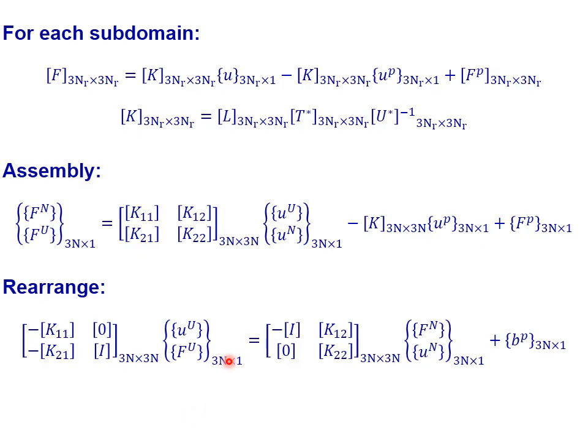The equation will be as follows. This is a force vector, and the equivalent stiffness can be computed from here. L is a diagonal matrix where each term in the diagonal is the area between the points. UP and FP are the particular solution for the displacement and the particular solution for the force, which are computed from the domain integrals.